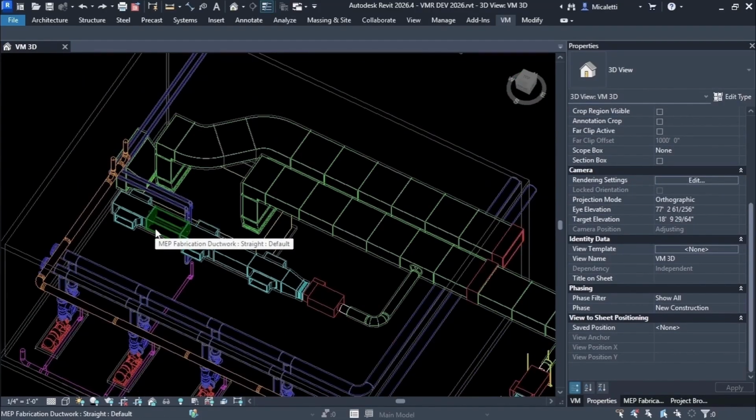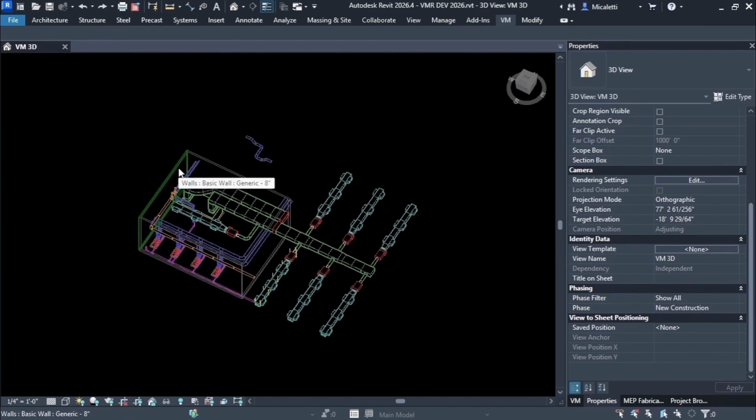So a pretty common standard will be to do packages by areas, right? Like you might have zone 4 that has 40 spools, so you want to make your zone 4 package. Sure. And this is an issue I run into with Revit right now: after an area is signed off and you get it all assembled in Revit, you have to remember to go write that area 4 package parameter into everything. And in this case, you're able to just select it in.